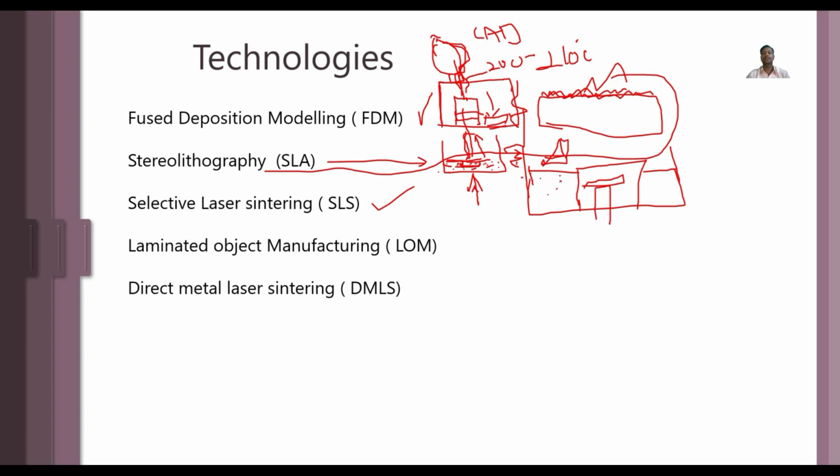So it's filled completely with the material required for printing. Then the laser will project onto the surface. Before that, the material gets moved from left to right by this spool, and it will form a layer on the surface. After that, it will immediately fuse. Due to this fusion, one layer gets formed.